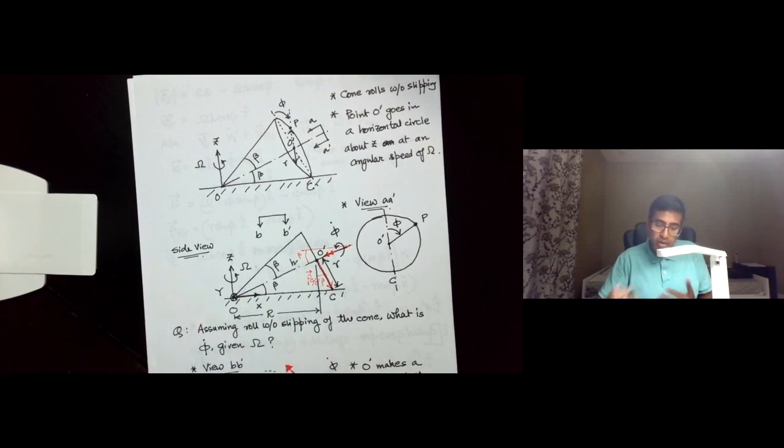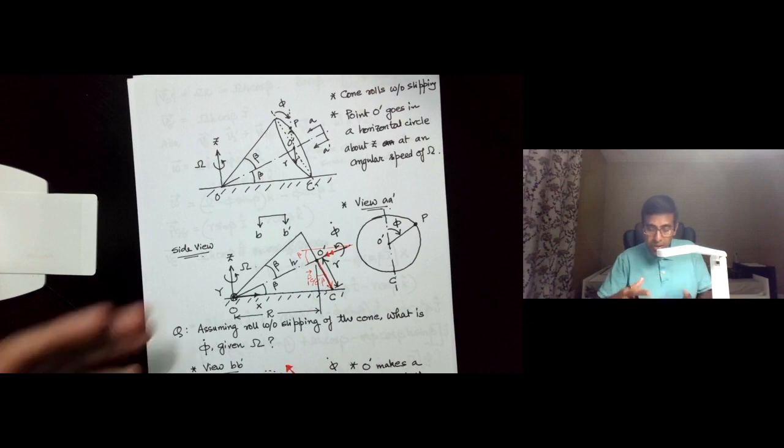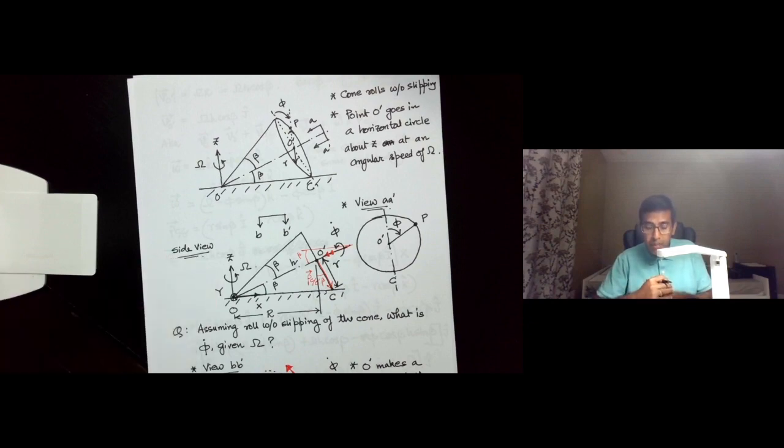So this was a problem where we did a kinematic analysis to find out what the spinning speed and the speed omega of a cone that is rolling without slipping is. What is the relation between the two? And for that we had to use some kinematic analysis. We used a rotating reference frame. We used the fact that 2 points on the same rigid body have a definite relation between them in terms of their velocities, and that relation includes the net angular velocity of the rigid body.